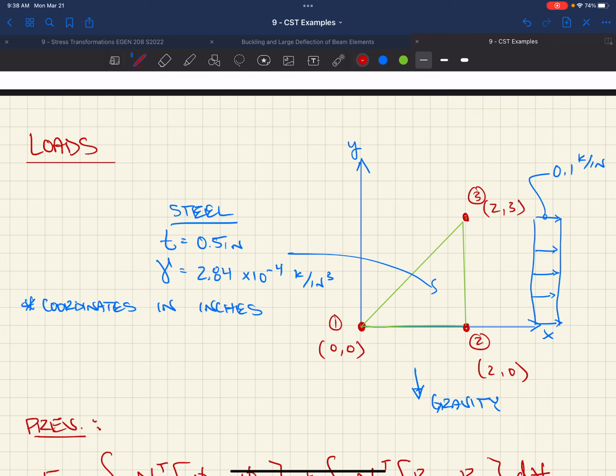That's why they call it a drilling degree of freedom, so it can rotate. And in that case, yes, you have a moment, essentially a torque on each one of these nodes. Then you end up getting 6 shape functions, 3 of which relate to the rotations, and you would have a moment contribution from that.